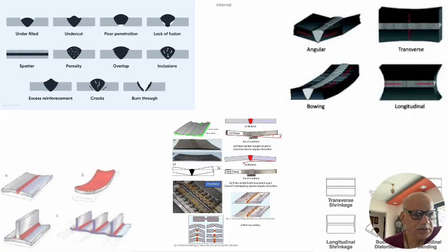And good welders I have seen, they are able to get them improved while they are welding only. Either they will stop immediately, do whatever correction required, either in the gas or in the shielding or in the angle of your torch or electrode or your other cleanliness issues if they are there for the porosity, and they will surely be able to improvise it.